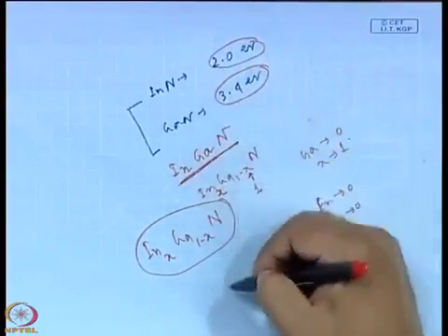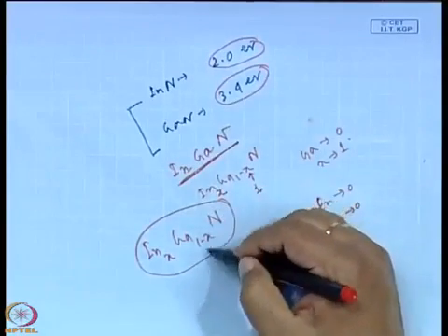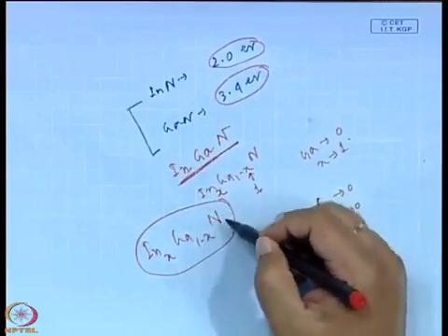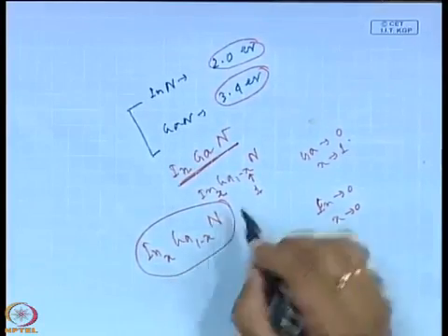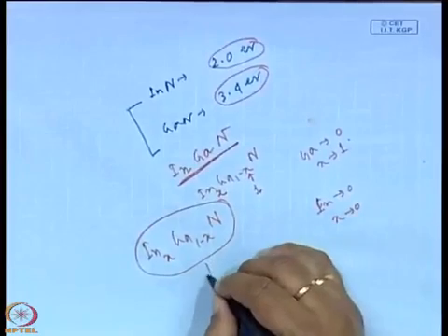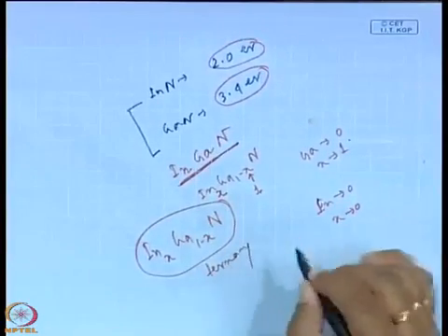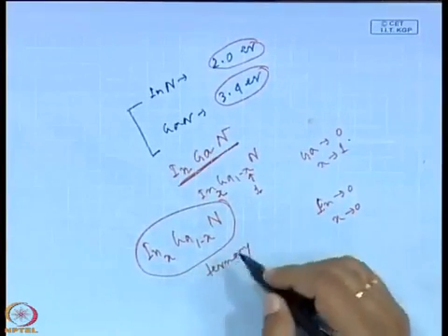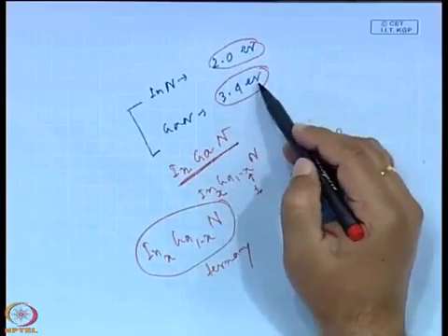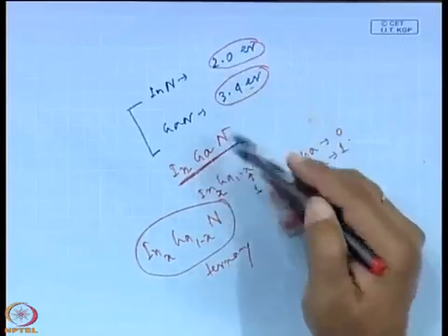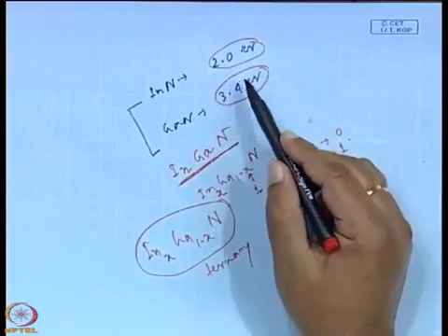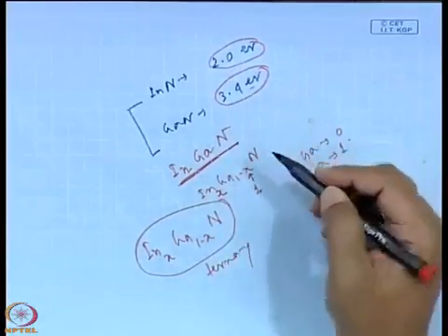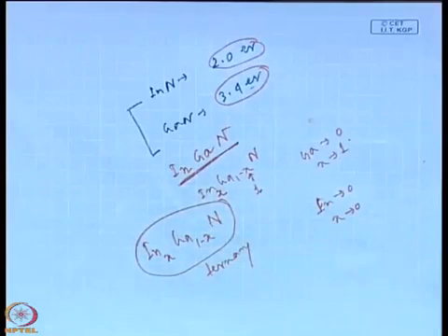So, continuously you can change the value from 2 electron volt to 3.4 electron volt by changing x from 1 to 0. That means it is a ternary compound whose band gap is between 2 electron volt and 3.4 electron volt. So, you can tune the band gap, and then the emission can be blue or ultraviolet or violet.